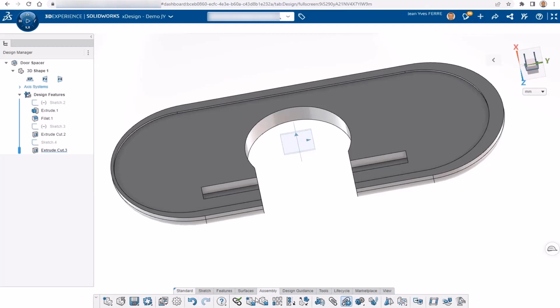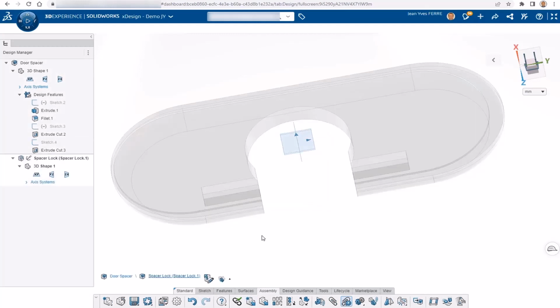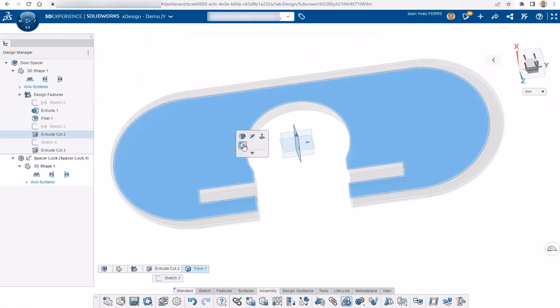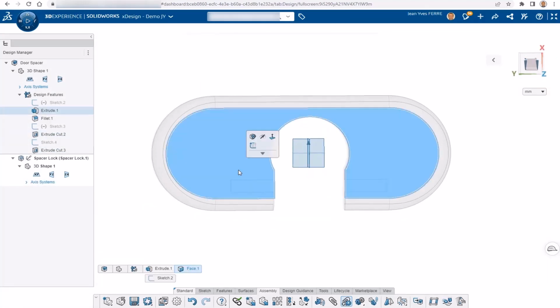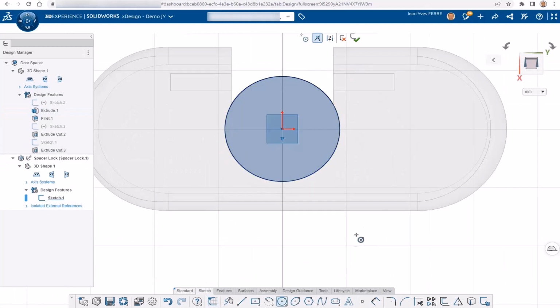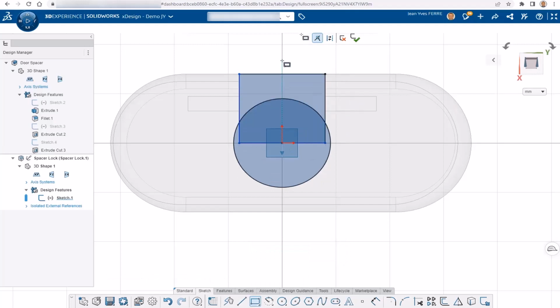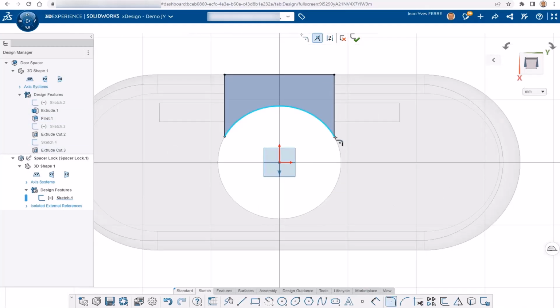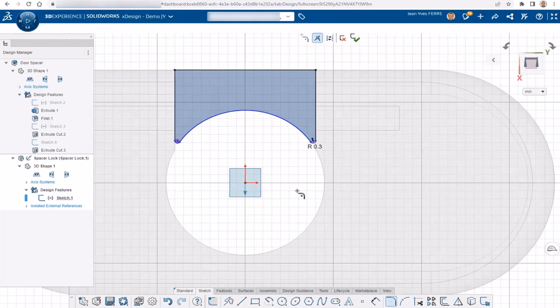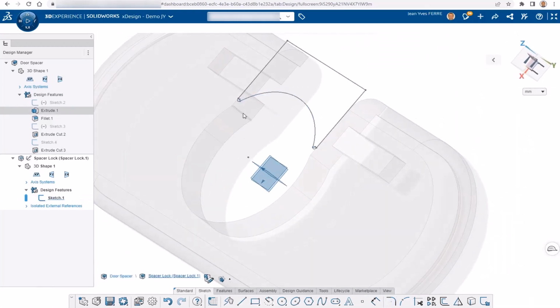Then I create directly the new part I need into my existing part and reuse existing contour. This is great, I don't have to create an assembly, insert the existing part and create a new part in the assembly. Here everything is done seamlessly and I love that. I create shapes of the new part based on existing one, so they will fit together. You may also have noticed how fillets are added with a simple sweep of the pointer to the right size. Who knows if the fillet is 3 or 0.3 mm? Here you don't guess the value, you just refine it once placed if needed.